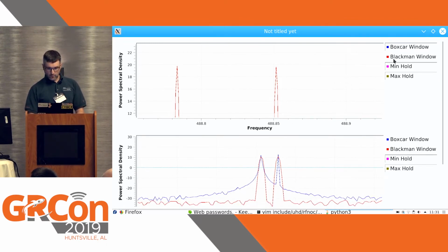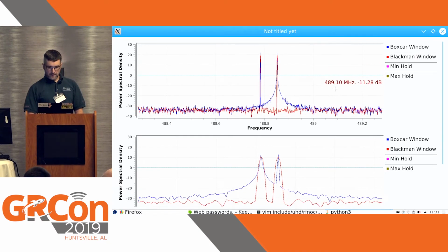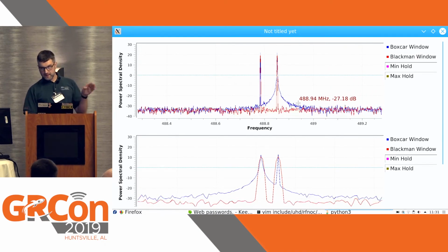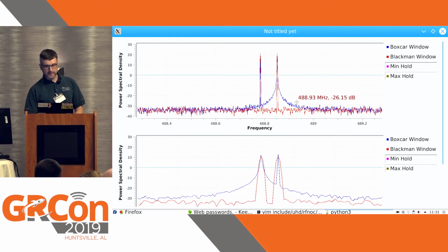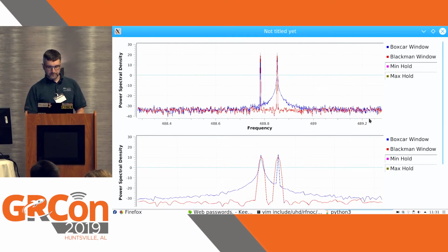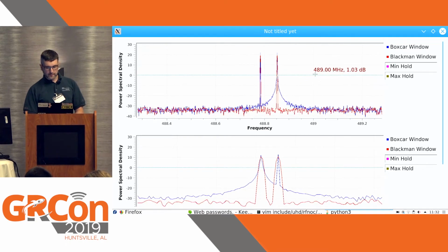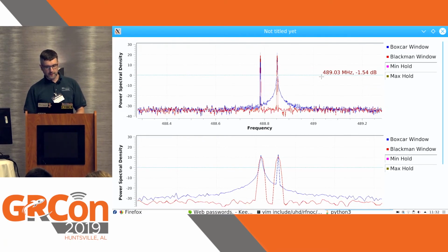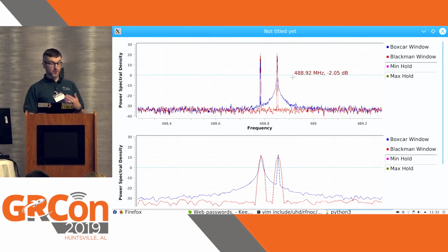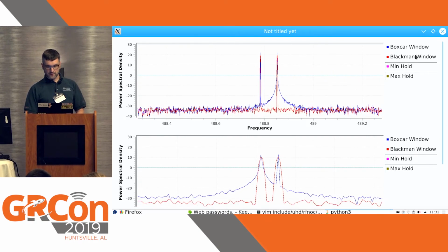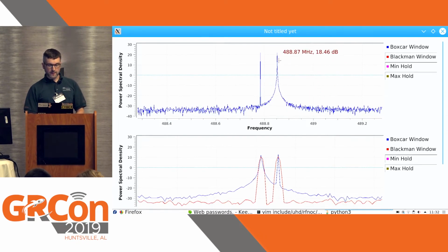And then finally, what is all of this here? Oh, sorry, I kind of skirted over that at the beginning. Before calculating our FFTs, we can multiply our signal with window functions. And that also matters. A window function is basically a time domain function that we apply to our signal first. If we don't apply a window, which we do not here, you will see these side lobes.